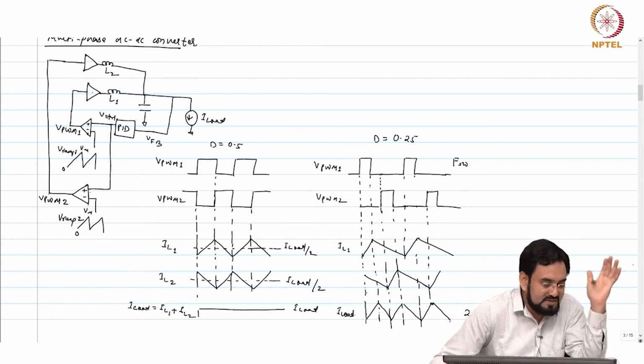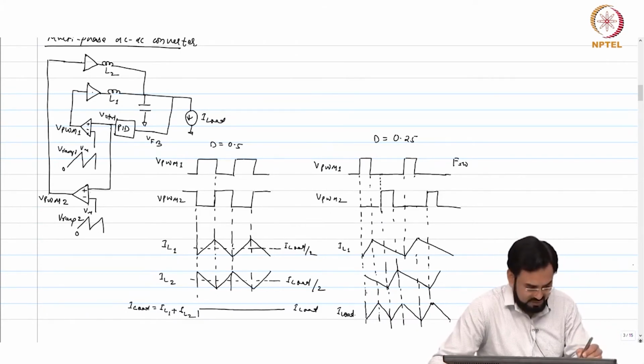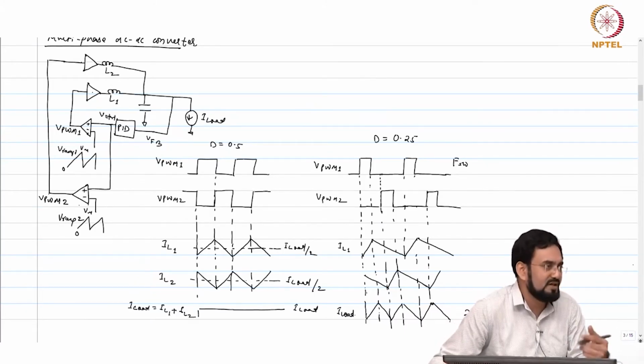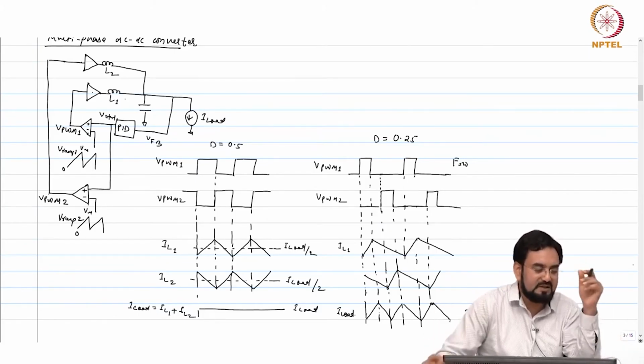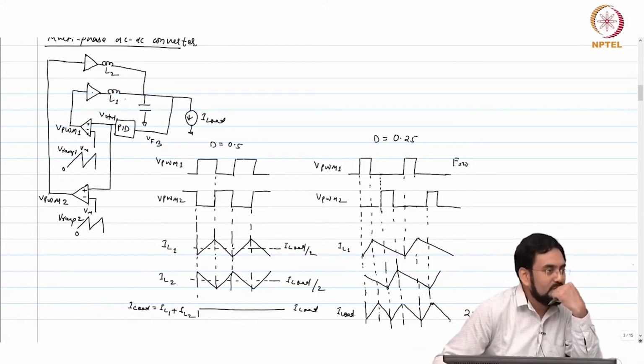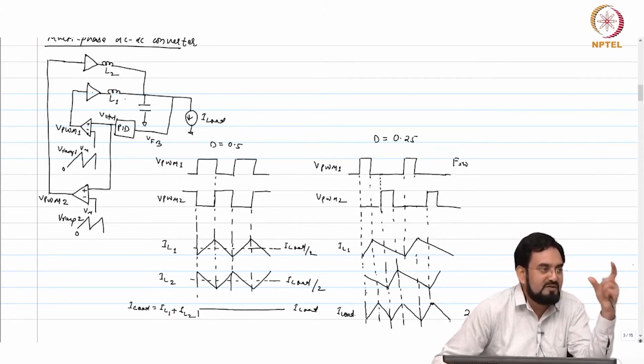Okay, even let us say the controller is not taking too much area and your control is common. So, extra you require PWM modulator only. So, extra comparator will not cost you much, but power FET are very large, and inductor is also an external component. So, it will basically make the cost almost double actually. So, what you do, you equally split the power FET. Instead of sizing the same, let us say you require 100 milliohm for 1 amp, and now it will be catering only 500 milliamps, so split into half, so that your total area of power FET remains same.